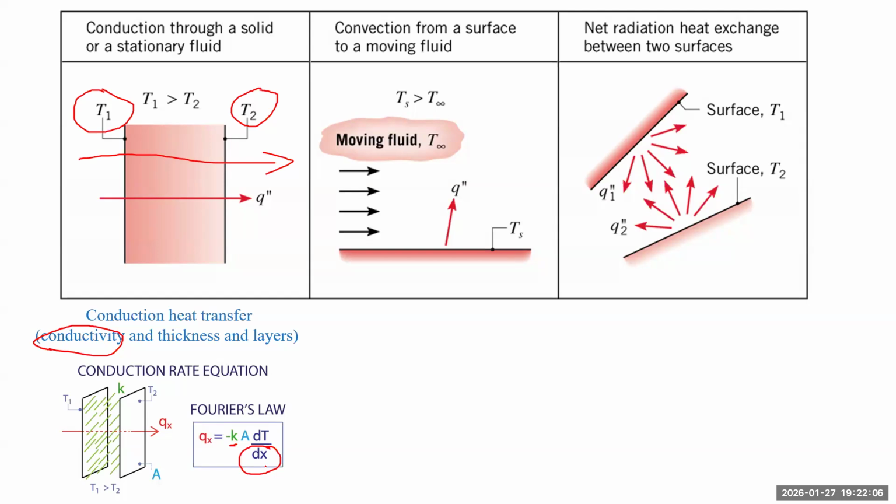Sometimes you need a supporting function or other functions, so you can add an insulation layer with a low thermal conductivity and also make it thicker. Or make your brick or concrete wall thicker. You can also reduce the heat loss or heat gain, that means the heat flow. And sometimes there are multiple layers in our walls, which also helps us lower the conduction heat transfer.